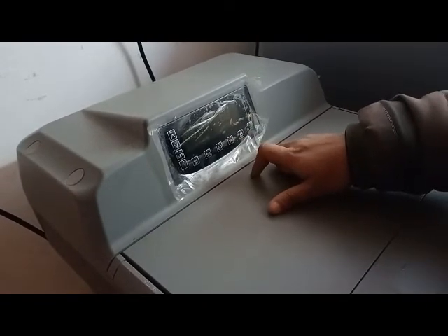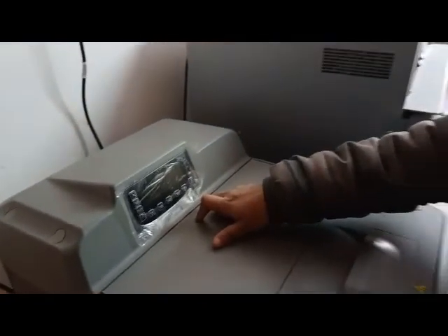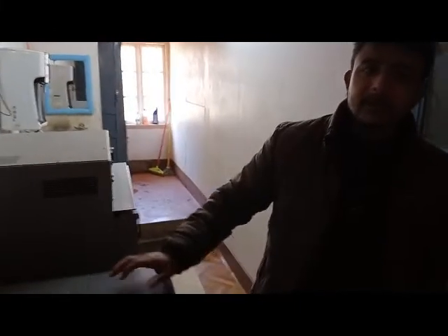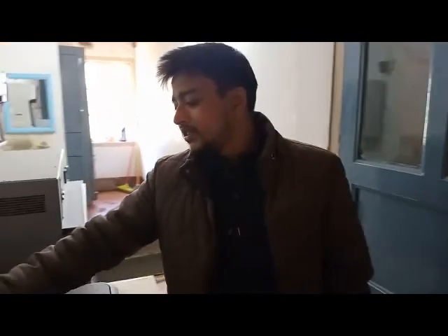For PLA we don't have any extra support. If we print this one in PLA, the PLA itself will give the support, fine. So no other support is required for PLA. Just in case of ABS and ASA we have QSR as the support, but for PLA itself is the support. So for PLA we don't need to use this one. For TPU we have the support system, fine, and we will use this one for dissolving as well as for ABS and ASA. So these are the temperature ranges we have here.